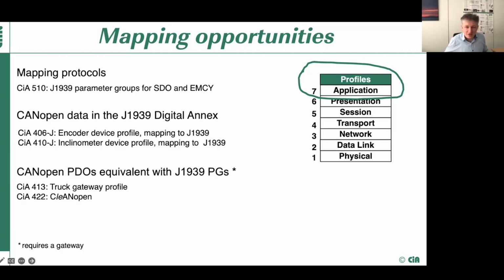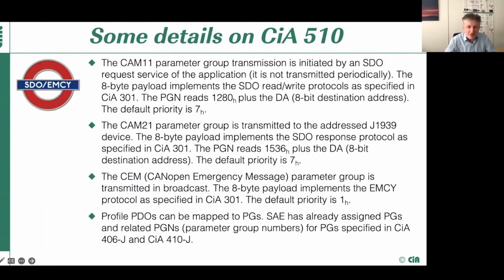They were designed in CANopen, and internally in the device, of course, there are J1939 networks. Interaction with them would also require knowing the PGNs and assigning the PGNs to very critical services and process data which may be needed from CANopen. But we discuss this in the next part. So then please, Holger explains to you about these basic interaction protocols of CANopen.